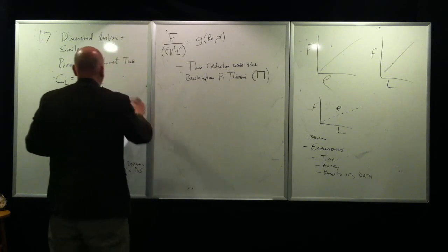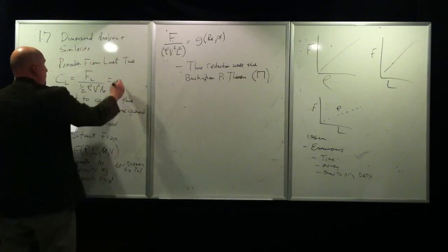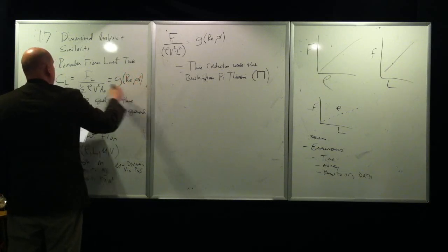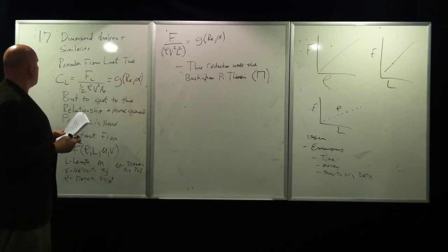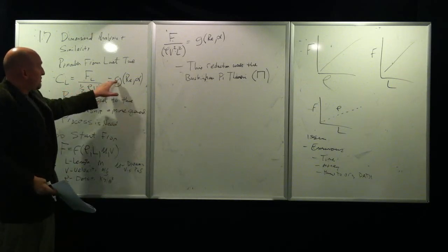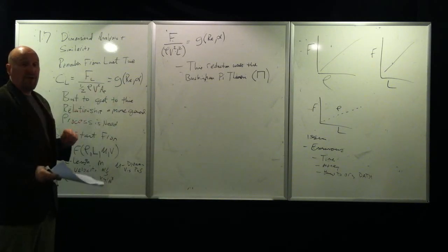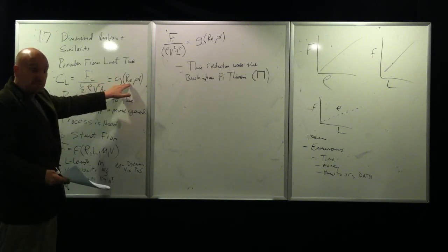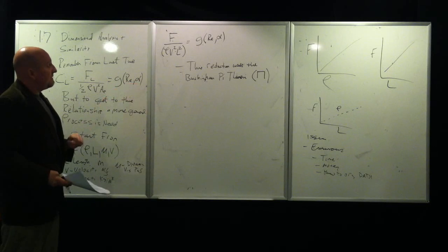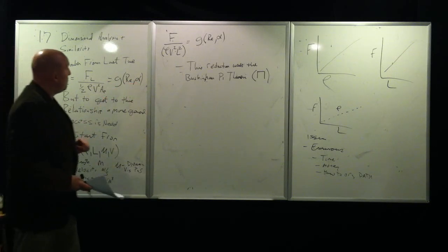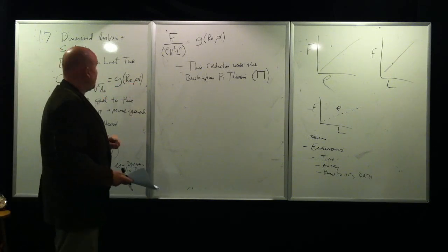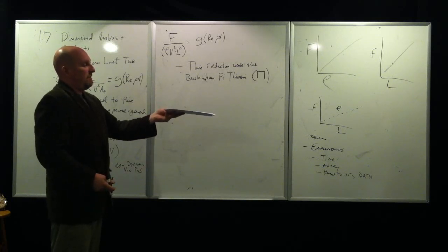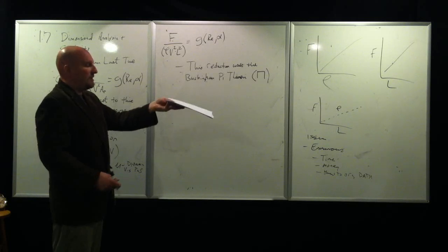So now we can say the coefficient of lift is really going to be some g function of Reynolds number and alpha. Coefficient of lift is just some sort of mathematical representation that varies as Reynolds number and angle of attack. And we went over Reynolds number, rho v L divided by viscosity, and angle of attack, how the area of your wing is represented into the flow.